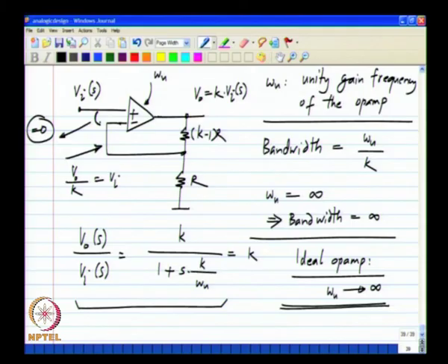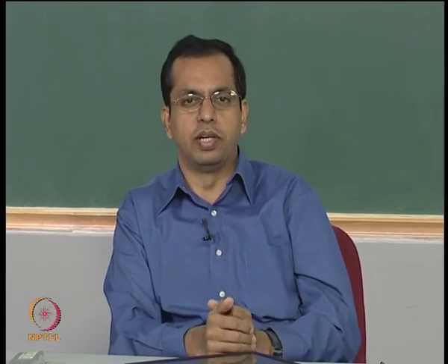So, many times the ideal op amp is presented first and then you are shown the actual op amp. We have gone the other way, we have gone from first principles to try and derive a negative feedback amplifier. For that we see that we need a block that senses the difference between two quantities and something that integrates the difference, and we can arrange it as a negative feedback amplifier. So, that is an amplifier in which the error is gradually driven towards 0.